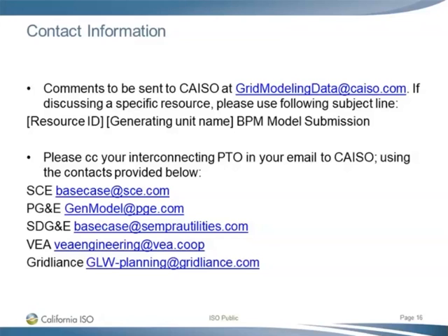That's right. So typically what's included or necessary in the EMT modeling documentation is any configuration that needs to be performed in order to run the PSCAD model, what compiler was used, what library files were packaged with the model, and some details about the model itself and what's included.